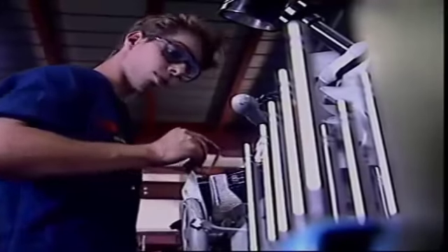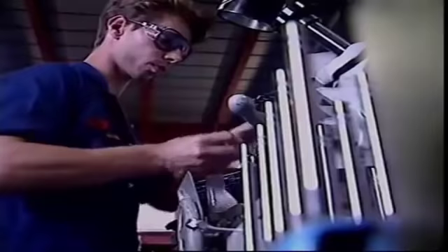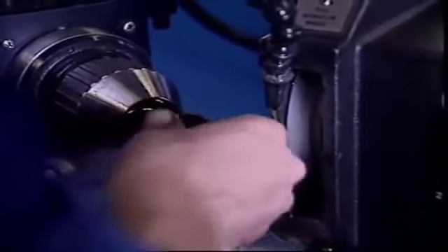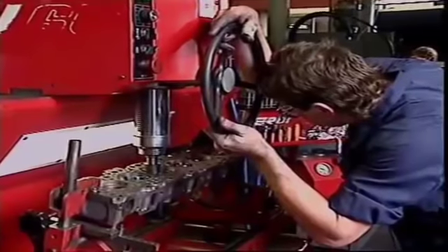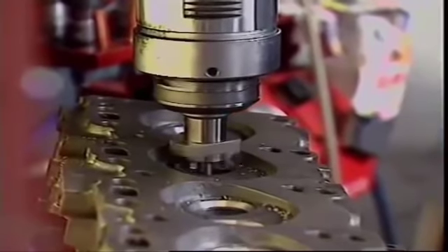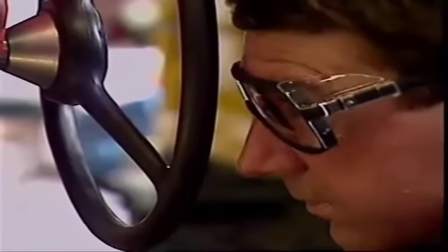Some engines use 30 degree or 45 degree face angles for inlet valves and 45 degrees for exhaust valves. Valve seats are often ground to the same angle as the valve face, but they can differ. The difference is called an interference angle. An interference angle allows for a quick bedding in of the valve face to the seat on new engines. It may also allow for slight changes in angle as a valve heats and expands.